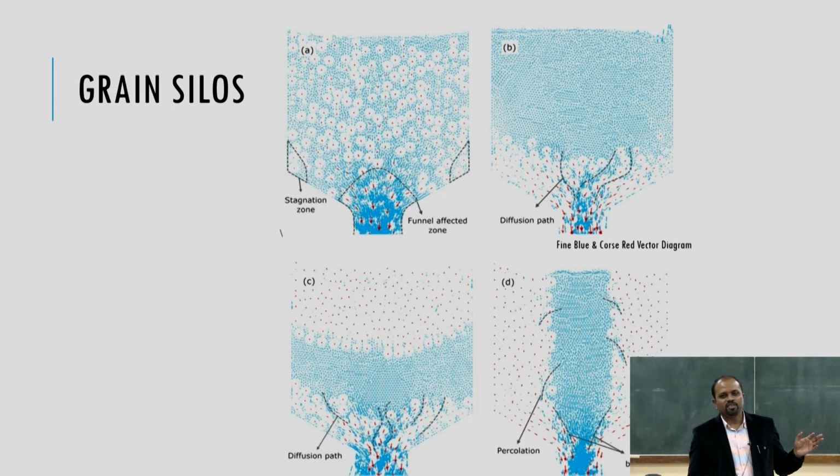So, in rat holing, a stagnant zone is created on the two sides of the silos, due to compaction also, right. And then if you open the bottom of the silo, the top grain will move out first, due to funnel flow. So, that is not desirable. You can go into the depth of this case, or you can study this. In this you can see how it is taken at the micro zone, or the particles too, right.